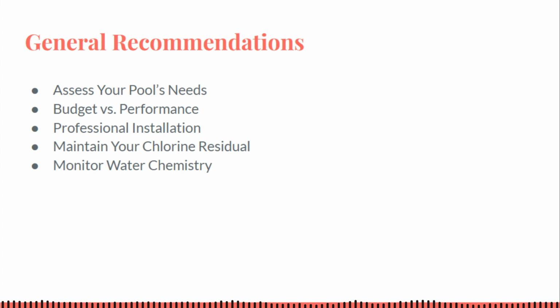Maintain your chlorine residual. Continue to maintain a normal low-level chlorine residual as required. Think of ozone and AOP as assistive technology that handles the heavy oxidation work, while chlorine, or another sanitizer, remains the constant background disinfectant. This combination will meet any pool safety standards and keep water microbiologically safe.